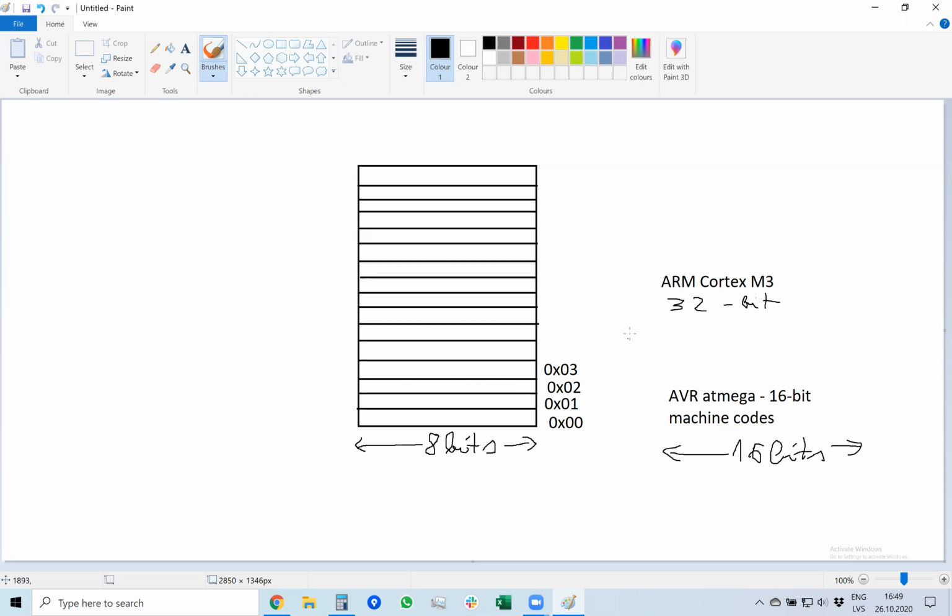But in reality, it is 8 bits wide, but it jumps by 4 locations on every instruction, and it actually reads 4 bytes simultaneously. So in reality, to make it cheap, the memory is 8 bits, but it jumps by 4 locations on every instruction, and it has this superpower, this hardware acceleration, that it can read 4 bytes at the same time of program memory.